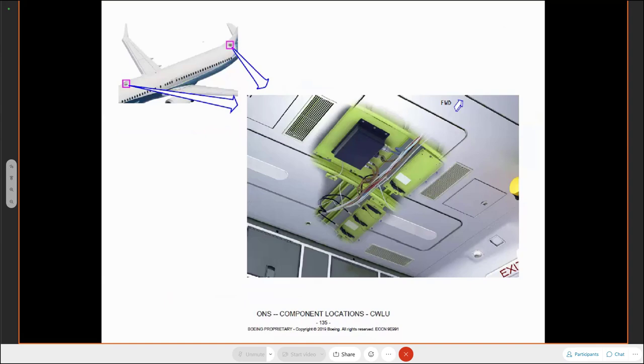If you are connecting wirelessly, then you'll also have to put a code in, an ID in, to ensure that you're on the correct aircraft for starters, but also to make sure that you've gone through the correct security handshakes when you connect a laptop wirelessly.